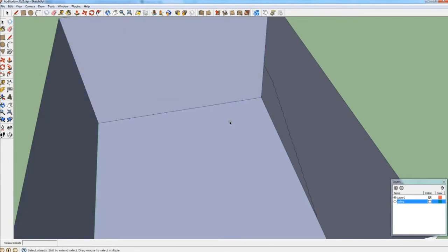Before that, I need to select this area just under the stairs, so that I can copy the whole area, actually not only the line that forms the stairs. So I select the move tool, control key, and go to the corner. I move a copy of the stairs, and then I place it at the other corner, because I need stairs at both sides of the auditorium.